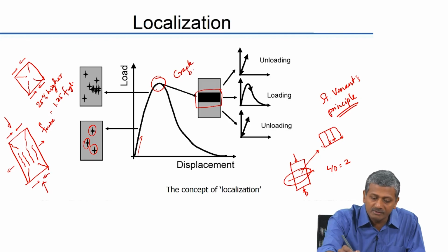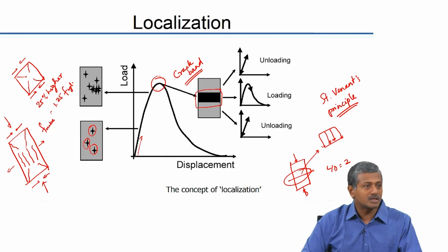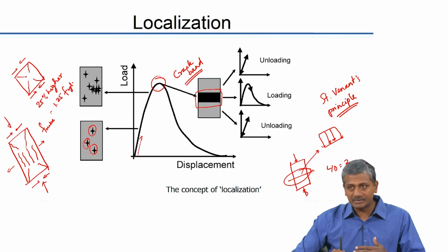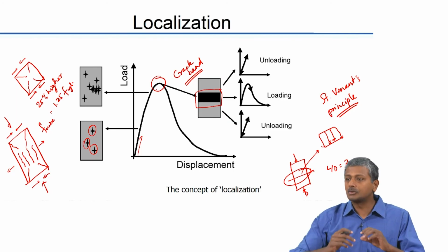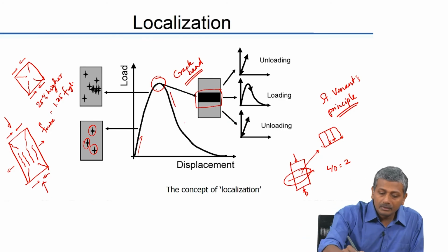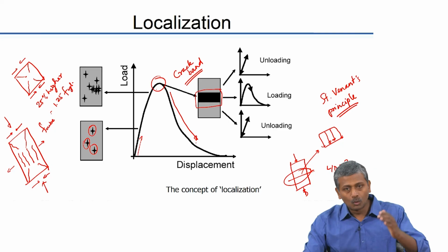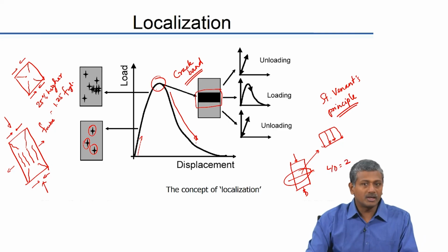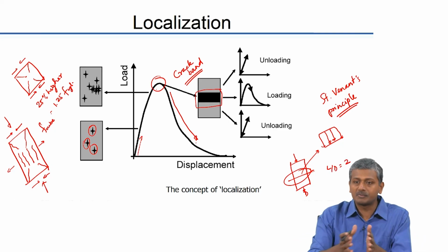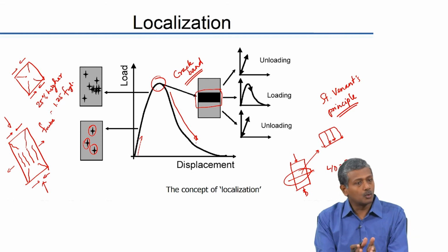So, those of you who are interested in fracture mechanics can take additional courses and you will learn about crack band theory in concrete. So, that is where this localized crack which is forming exactly in the center of the cylinder starts to grow. So, as the crack starts to open up, the specimen displaces more and more with lower and lower levels of load. So, you do not need to give higher levels of load to make it displace the same amount. So, the displacement is registered now at lower and lower levels of load.